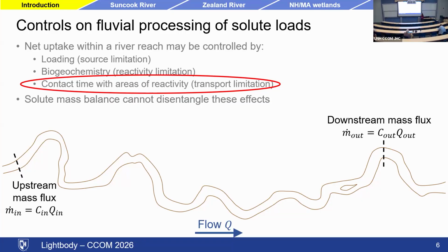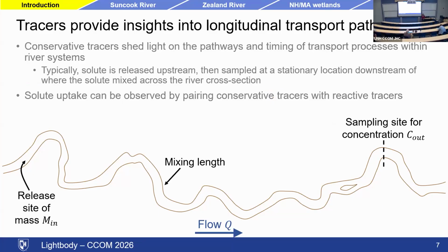And one of the tools that we can use is an introduced tracer. So a dissolved tracer is a substance that we add. Hopefully it's non-toxic. Hopefully it's present in fairly low concentrations so that we can easily measure it down to low concentrations. And hopefully it's conservative, so it is not reactive. And therefore we can measure how that dissolved substance that we've added in known quantities moves. And when we look at that, we therefore know how other substances that may be reactive, that may be more toxic, that we may actually care about, move.